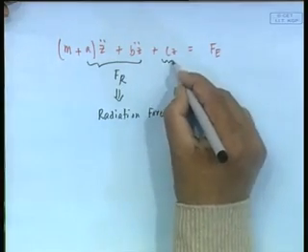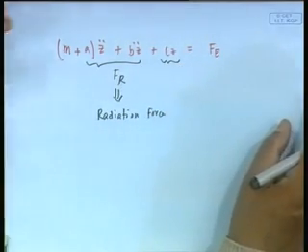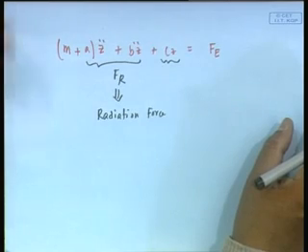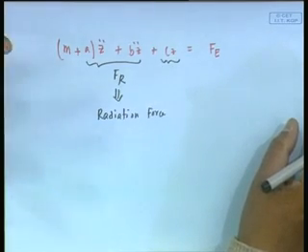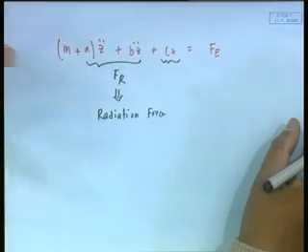This is my hydrostatic restoring force, not hydrostatic force by itself, because remember that integration of pressure up to the mean water line is balanced by weight. Archimedes said that long back. It is only that displacement, the additional part, that has given additional pressure. That is why it is called hydrostatic restoring force, but not the Archimedes or buoyancy force per se.